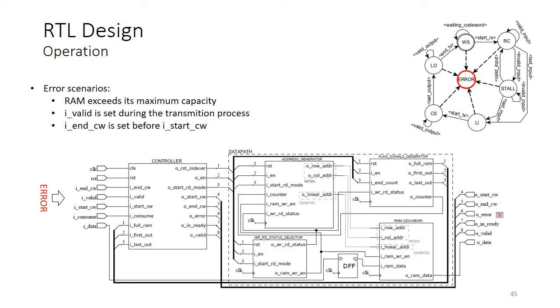The error state may be reached whenever the RAM exceeds its maximum capacity, if iValid is enabled when the interleaver is in the transmission mode, or if iEnd code word is set without any previous iStart code word.